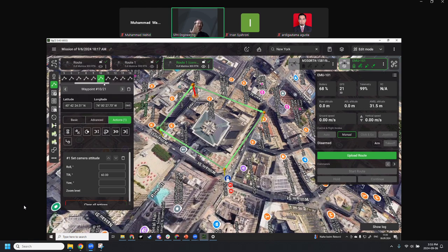As we've mentioned with the AGL tolerance, you can use a lot of waypoints. You can generate them to follow the terrain as closely as possible. But for example, if there's one area that is giving you trouble, there's a sudden elevation change and too many waypoints are generated, then you can convert the route to waypoints and either delete some waypoints or modify the speed or change the altitudes a little bit and micromanage around your issues this way.